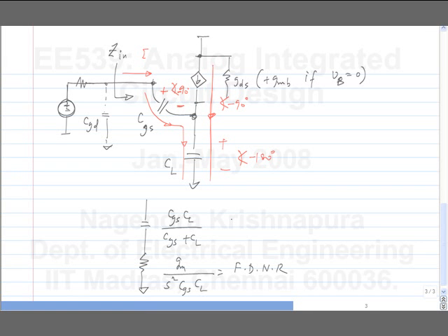That you have to analyze based on the exact situation you have, because you not only have these parts, but you will also have another capacitance which is CGD in parallel with the entire combination. And when you include the effect of GDS and GL, the expression becomes more complicated, but you will have one component that corresponds to the frequency dependent negative resistance.